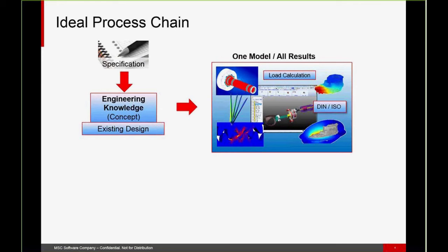And this would be the big difference to the process before. So we try to perform simulations in parallel. If we are not able to do it because the solvers are so different, then we need an automated process to perform the serial simulations automatically. This would then, of course, save the time you need to convert the data, and it would simply save the user's time because the work is done by the computer. That's the principal idea, and this is what MSC is trying to achieve and what we are working on.